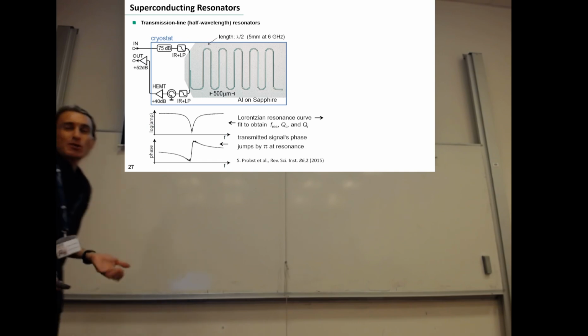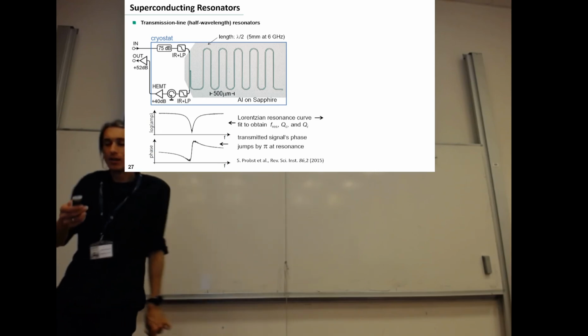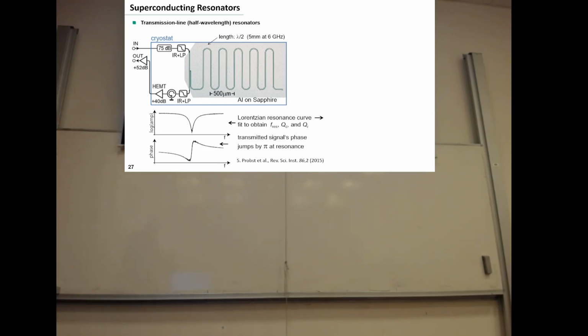Resonators always also show a phase shift when you move to the resonance frequency. You can also measure this using a vector network analyzer, and basically you typically get this step by 2 pi in the phase. Simply because if you drive slowly, a mechanical resonator will oscillate in phase. If you drive faster and faster, it will actually show this anti-phase oscillation.